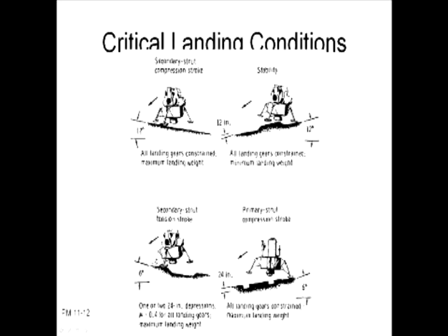We're looking for a secondary strut, and we picked an orientation that really taxes the stroking of the secondary struts, which would have been landing up into the hill in that particular direction. Then we got a downhill landing, and one that taxes the primary strut stroke to maximize it, which is 1-2-1 downhill.